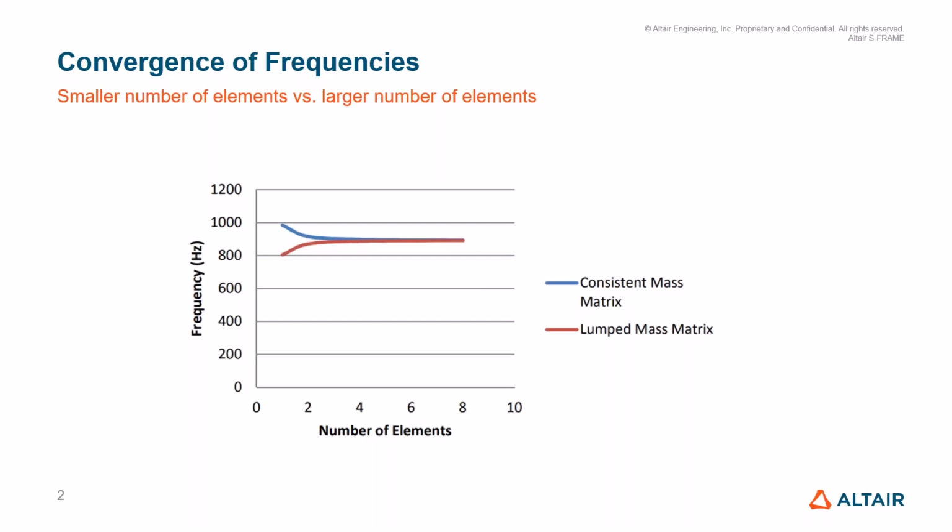Let's not forget that the building's natural frequency is an important value for structural engineering, as we will try that this frequency never matches the frequency of the seismic waves at the desired location, which would inevitably cause the structure's failure. So with this quick demo, we hope to have been able to prove the point of modeling more realistic structures to reach more accurate results to design safer structures during dynamic loading scenarios. Thank you very much for your attention, and back to you, Matt.